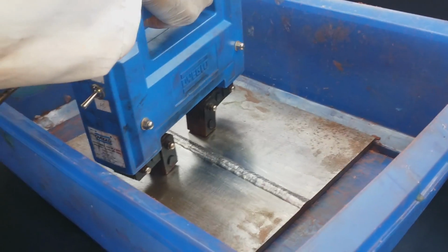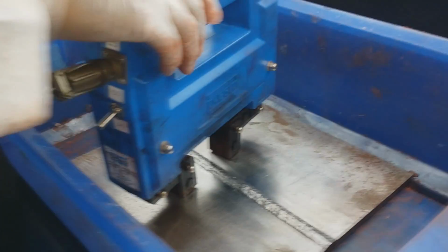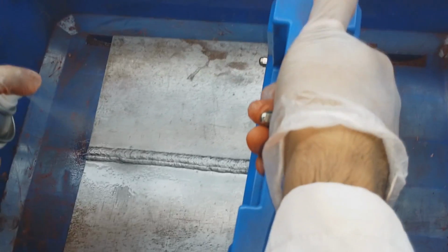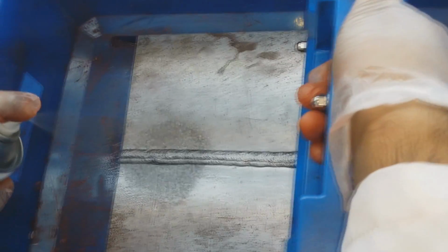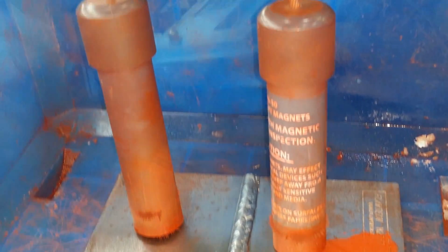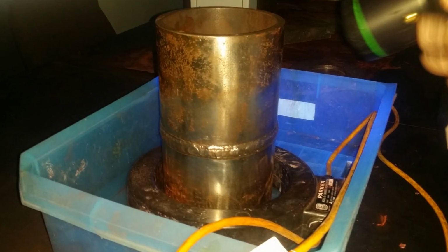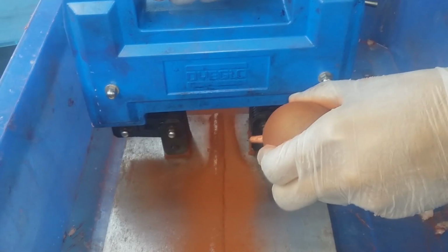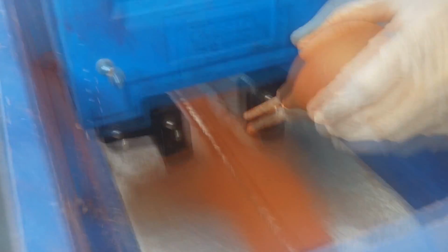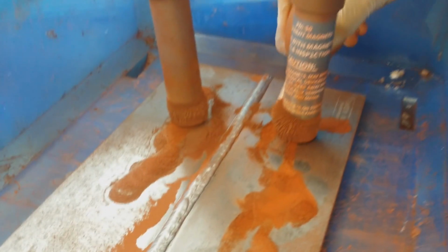In this short video we'll show the methods of magnetic particle testing inspection. There are a lot of methods of MT inspection. In this short video we'll show some of these methods, which inspect by using dry visible continuous technique, permanent magnet, wet visible continuous technique, and longitudinal magnetization technique. First of all, we'll show the inspection which is using dry visible continuous technique and permanent magnet.